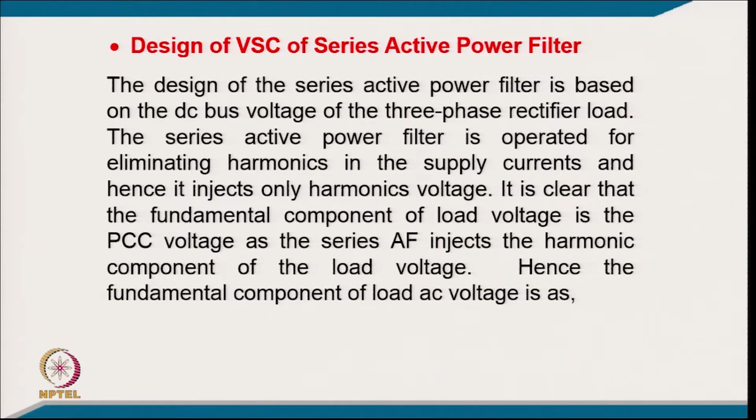The design of this series active power filter is based on the DC bus voltage of the 3-phase rectifier load, and the series active power filter is operated for eliminating the harmonics in the supply current, and hence injects only harmonic voltage. So, it is clear that the fundamental component of load voltage is the PCC voltage, as the series active power filter injects the harmonic component of the load voltage.